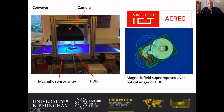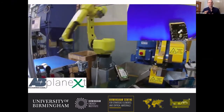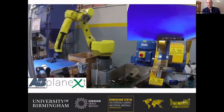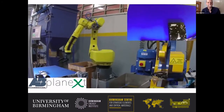And with a European partner, we started to develop a line where you put the hard drives onto a conveyor system. Underneath, there's an array of magnetic sensors. Above it, there's an optical camera, which is drawing this line around the hard drive. And that information is relayed to a robotic system. And what the robot's doing is it's essentially working out where the magnet is in the drive. And then with a very clever piece of software, it's guiding the hard drives into a cropping system, and it's just cutting the corner off the drive. So it's removing the magnet containing component.